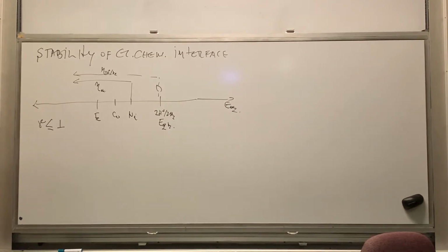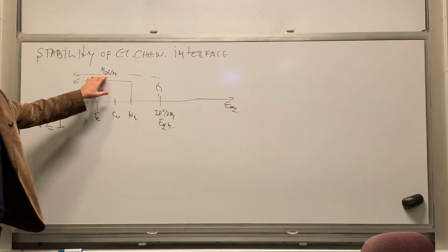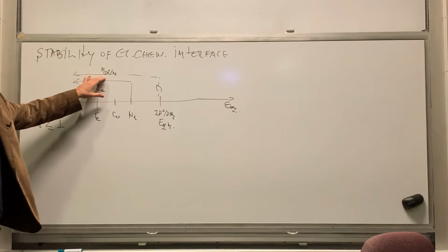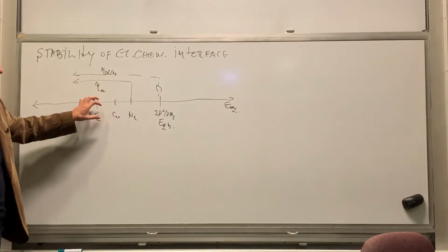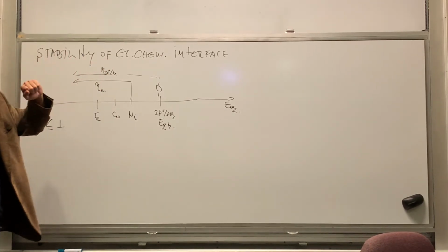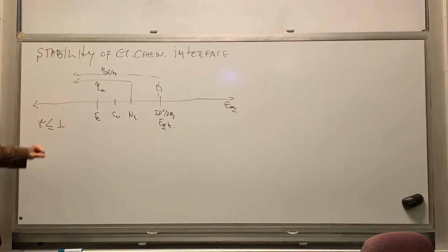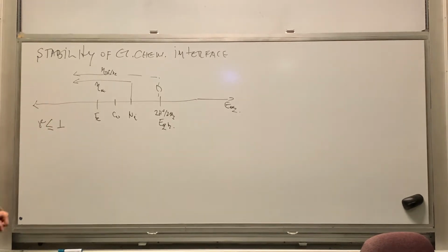Basically what that really means is, if you measure the current related to electrodeposition, let's say you think it is 1 amp, because you have a concurrent reaction going on, actually 1 amp per centimeter square, for example, is not entirely related to nickel, cobalt, or iron reduction, but part of that current is related to hydrogen evolution or hydrogen reduction. And so for that reason, this gamma, which is the current efficiency coefficient, is less than 1, right?